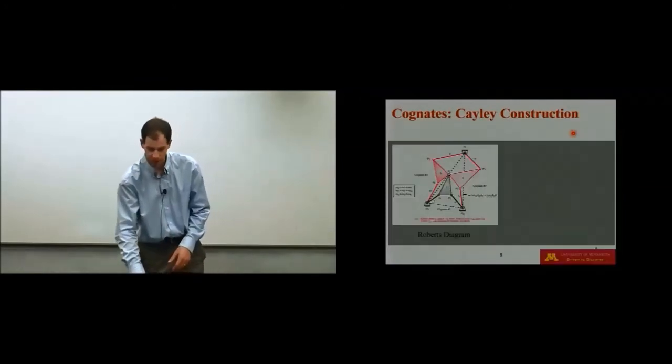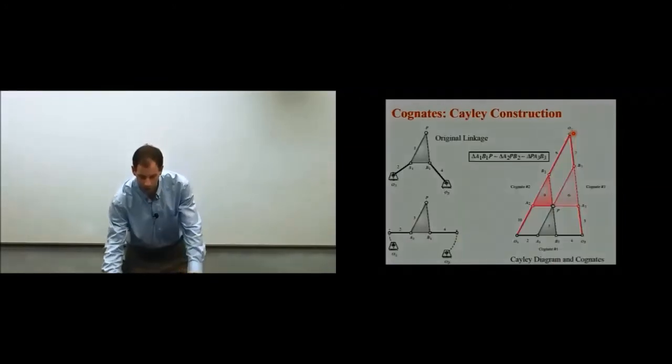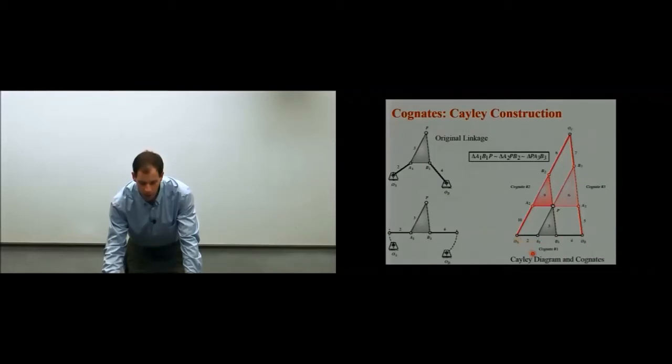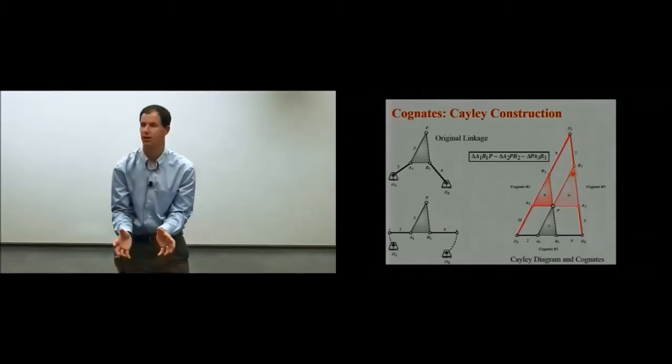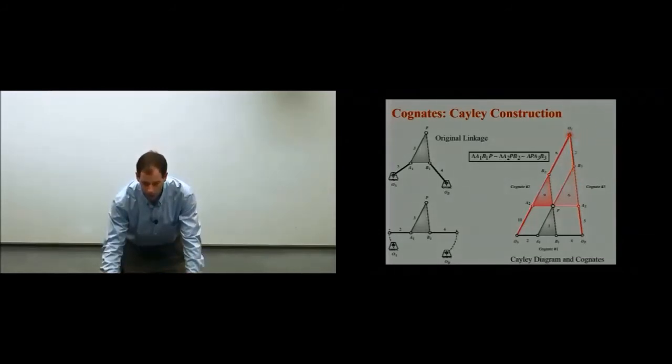The very last step that I do, and maybe I'll leave it on this page right here, is I take these two ground pivots, OB and OA, and I pull them back down to their original conditions or their original points. And in doing so, it moves the entire mechanism, if you will, pulling OC down to a new ground pivot. So OC is kind of floating in space right here, right now. Once I pull OA down and I pull OB down, you can imagine this guy's going to come down and locate somewhere right around where I've got my laser pointer right now.